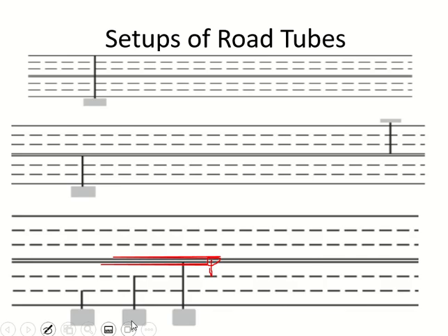So that means I cannot count just one lane. The middle lane cannot be done alone. You will have the middle lane and the other lane which is to the side of the road, so in this case you will have the count of two lanes. You take the count of two lanes and subtract the count of the other lane from it. If the count is required for each lane separately, you have to use the count of one counter to correct the count of the other counter as well.